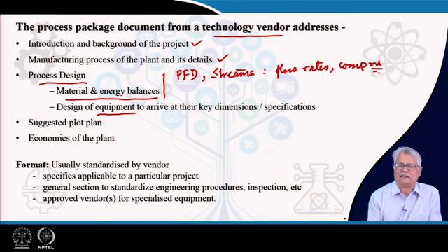The communication has to be in terms of drawings as well. The first thing that you have are the general arrangement drawings. That means, if it is a distillation column, what you will have is a gross dimension marked on an elevation drawing, a little bit of detail about the location of the nozzles, possibly the elevations at which the trays will be fixed, the height of the skirt support will also be there, and naturally whatever is required to have a general idea.